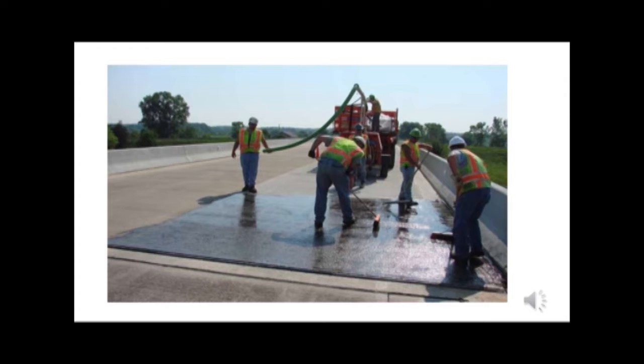Paving of the bridge is done so as to ensure the uniformity of the overall road structure. That is, the approach road should not be different from that of the bridge road. The color, the nature, the smoothness should be the same. Also, once the seal layer is laid, we provide the mastic asphalt. We heat the mastic asphalt on site, and we allow it to flow over the surface, and then properly layer the entire deck slab with it, followed by the wearing course.